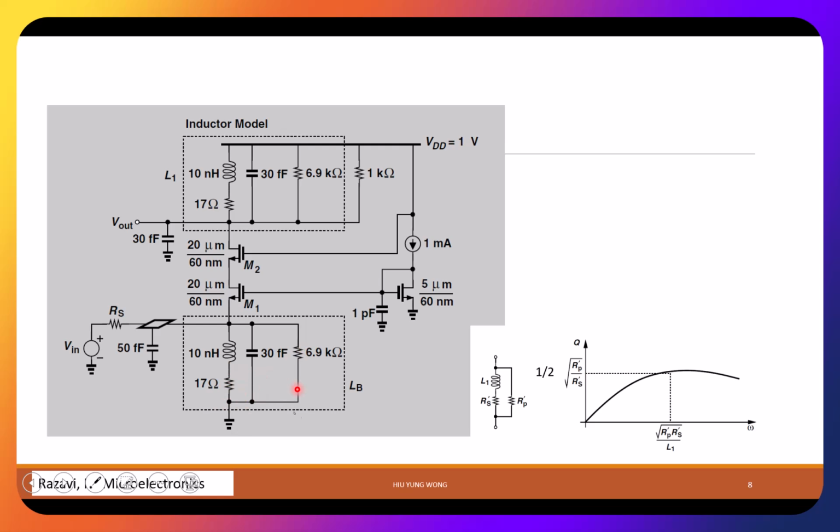This is LB. The whole LB has the inductance, series resistance, parallel resistance, and parasitic capacitance. You only know this parasitic after you have done the layout. This you already know, and it also depends on what type of inductor you use. And this is the pad.